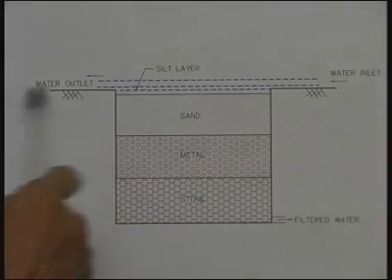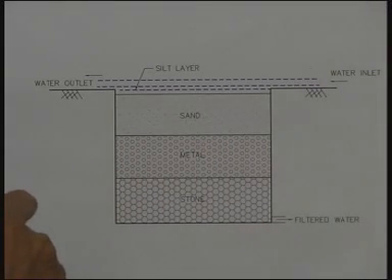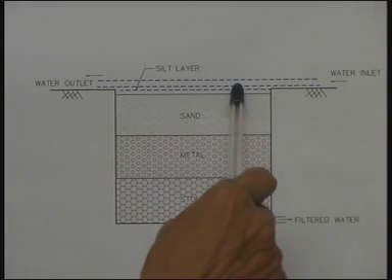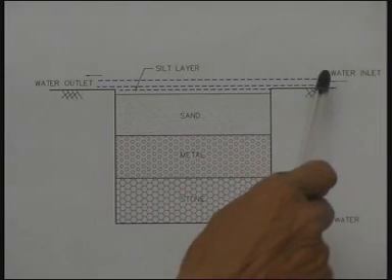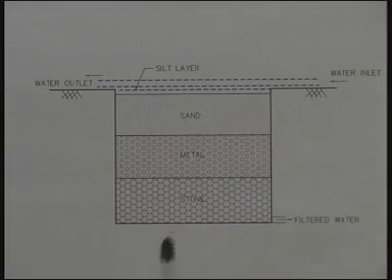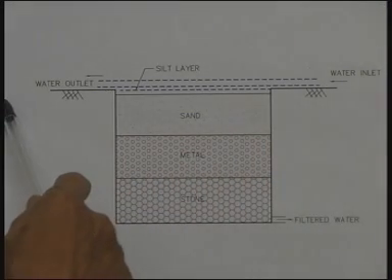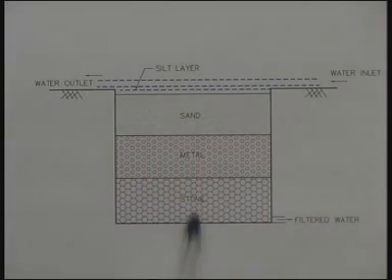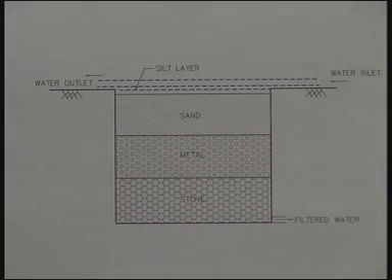Water will overflow this sandy bed and goes into the street. So, the rate at which the water enters the pit would be much higher for ordinary precipitation of 1 inch per hour, and most of it would go over the pit because the infiltration rate is limited by the design of the filter bed.